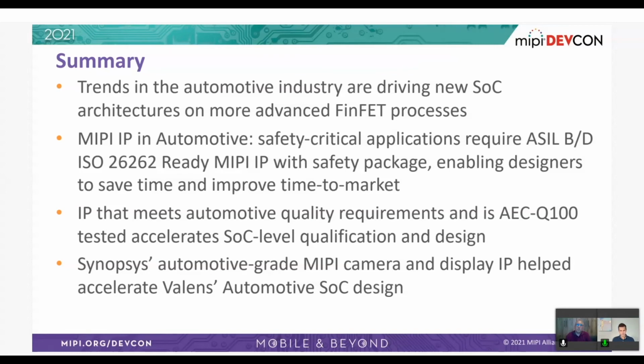So the summary for this talk here, we talked about the trends in automotive that are driving new SoC architectures and using advanced FinFET processes. We talked about MIPI IP in automotive, these safety critical applications that require ASIL B, ASIL D ready automotive-grade IP, and how this can help designers to save time and accelerate the development.